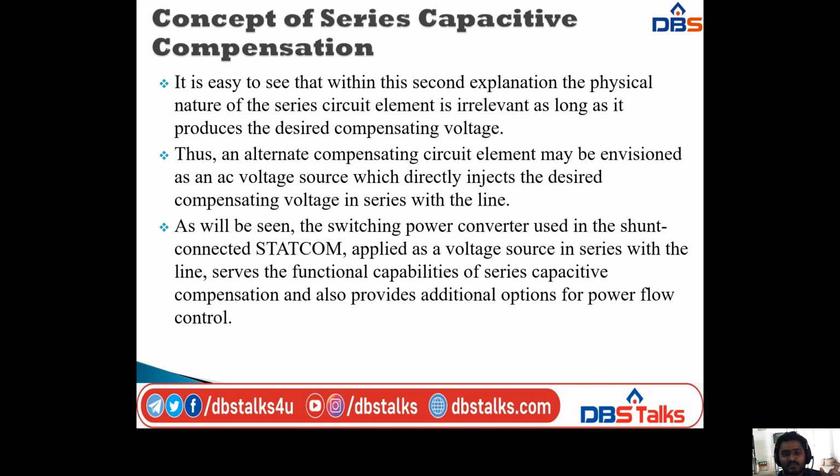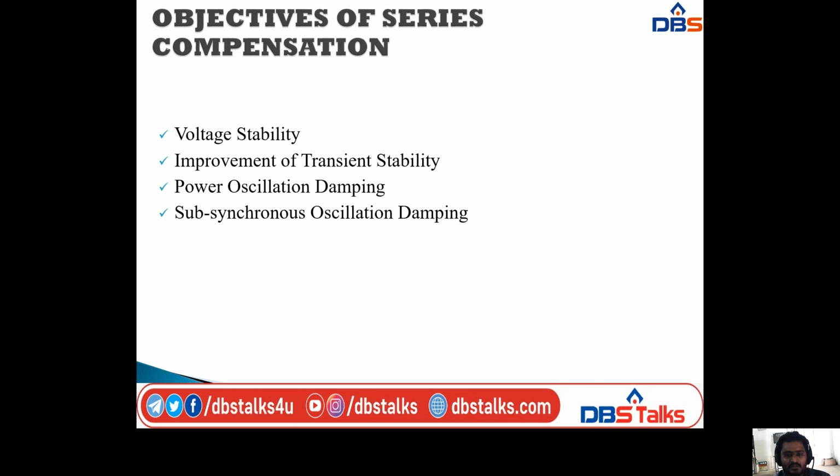So it serves the functional capabilities of series capacitive compensation and also provides additional options for power flow control. So that is the concept of series compensation.